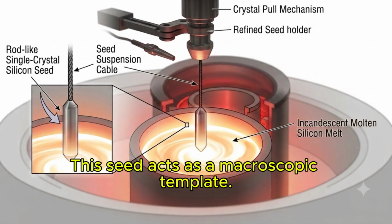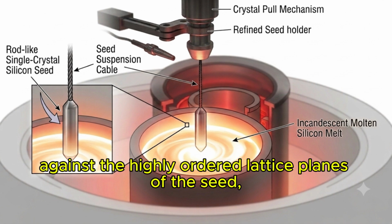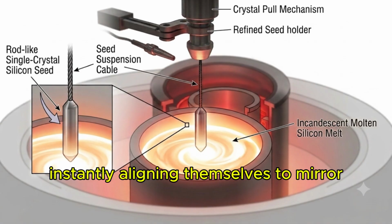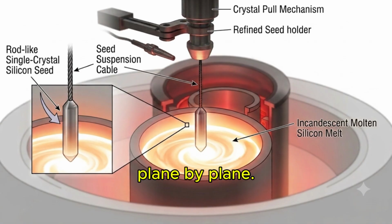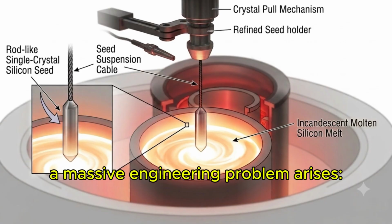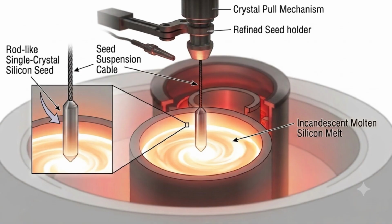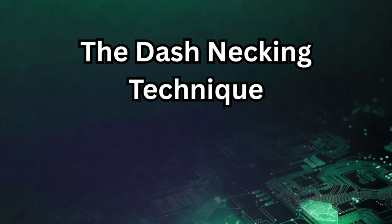This seed acts as a macroscopic template. The uncoordinated, chaotic atoms of the molten silicon bump against the highly ordered lattice planes of the seed, instantly aligning themselves to mirror its exact atomic orientation, plane by plane. However, the moment this cold seed touches the white-hot melt, a massive engineering problem arises: thermal shock. 3. The Dash necking technique, eliminating dislocations.